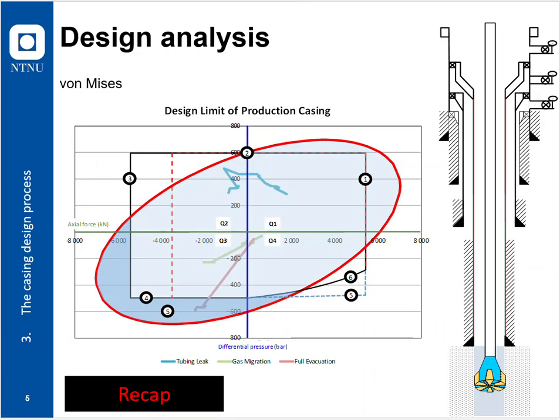Very often, both pipe and a lot of other products coming out of pipe manufacturing are no longer following the standard API recommendation. They are, call it, much stronger and much more improved. That's my observation, at least from what I have seen. And very often, when it comes to couplings, there's an abbreviation called HC, which means high compression. These are the things that you very often find yourself applying in the industry.